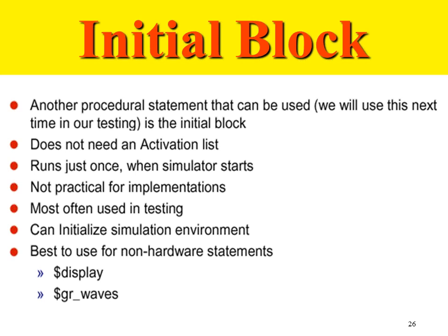Okay. Let's say there is an LCD display on your board. Normally, when you power up the board, the LCD will show you the name of the company from where you have purchased that board, right? What if I want to display my name when it powers up? How do I do that? Let's talk about embedded for a minute. I will write my own logic to display my own name, or my own custom message, on the LCD, and reprogram the ROM on the board, where it will pick up that ROM contents, transfer them, and display the appropriate custom message when you power up the board.